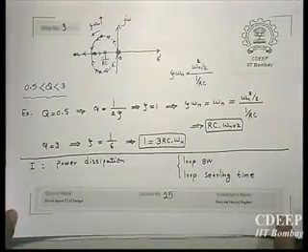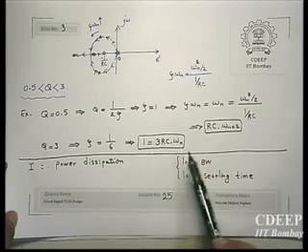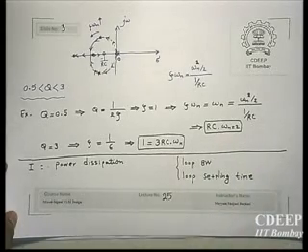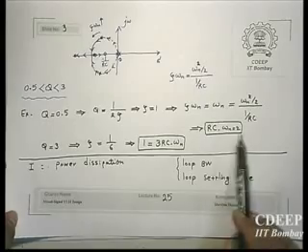And then if you choose Q of the filter, or eventually zeta omega n, according to the trade-off between stability and bandwidth, eventually you have RC omega n known, right?